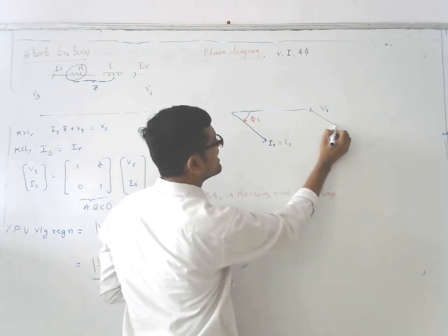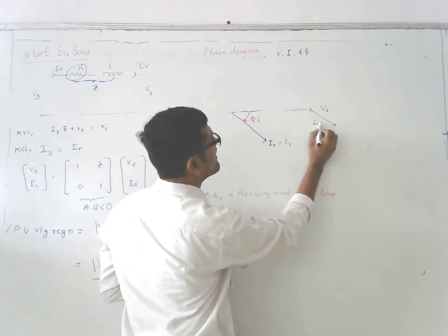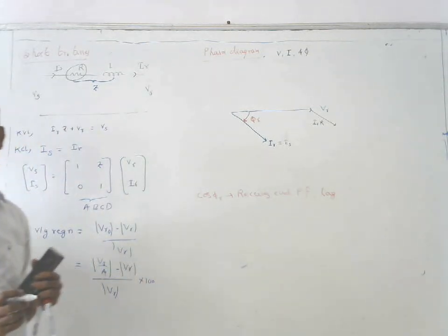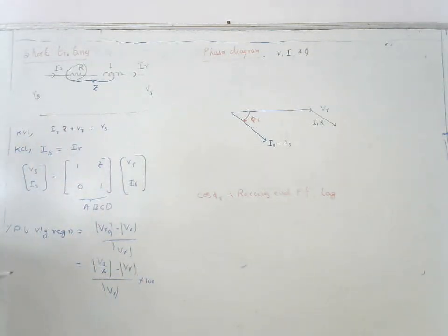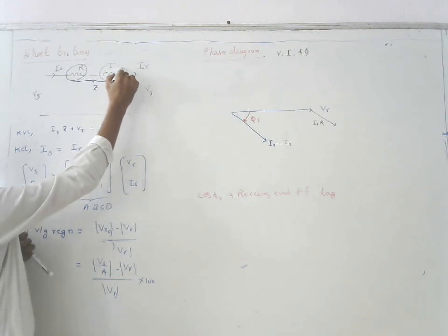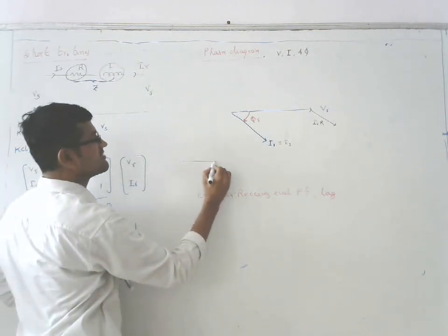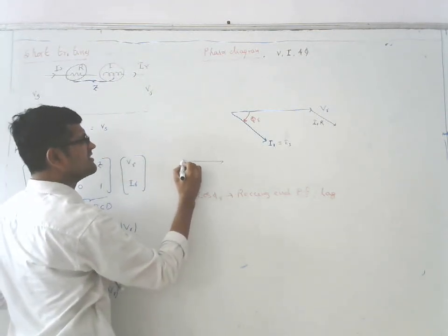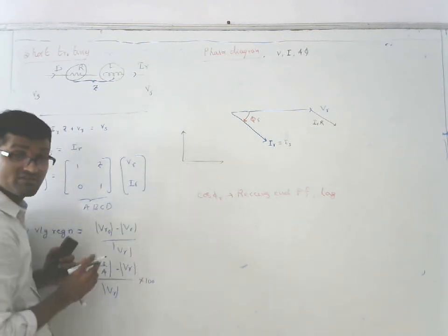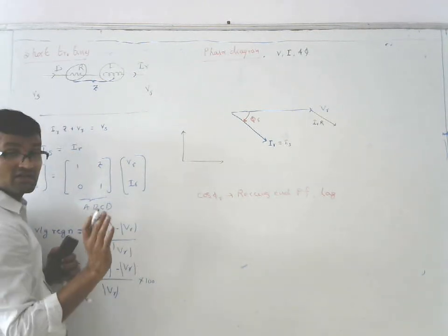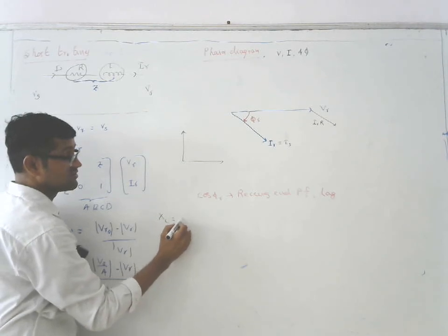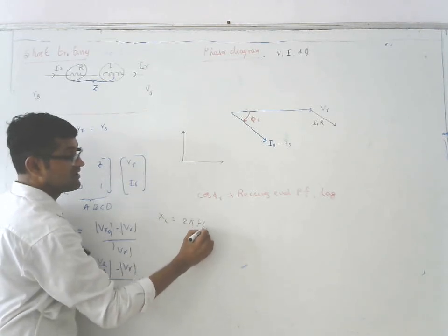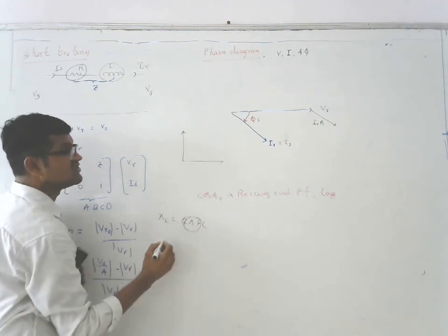Now next, the inductor. You know the phase difference between resistor and inductor. The resistor is along the real axis. The inductor is j omega, the frequency term. We discussed already how to find XL, which is equal to 2 pi f L, omega L. This frequency existing in the numerator means plus j. Plus j means plus 90 degrees, exactly 90 degrees.